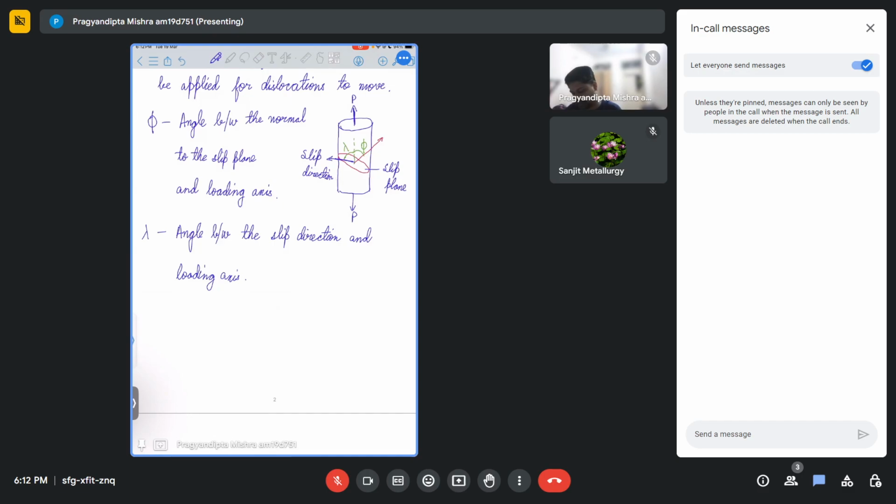So now we want to find shear stress, right? We have the load. We can find the component of the load along a particular direction, but we also need to find the area, right? Not just the load. So let's say that the area at the top face, basically this face, was A, and this area here is A dash. So how can I write A and A dash? How are they related?